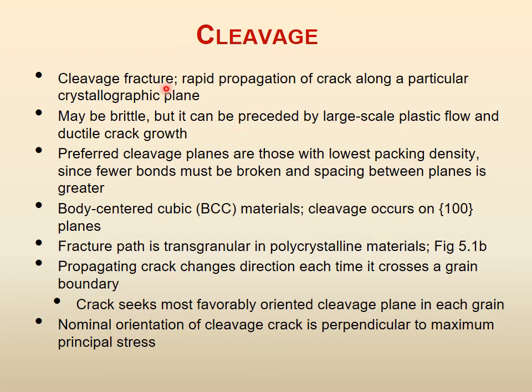One thing is that cleavage can be totally brittle. There is a big fracture all through and there is a cleavage surface. But on the other hand, there may be large scale plastic flow and ductile crack growth, and because of some sudden change in mechanism, now all this has changed to cleavage. So originally there is large scale plastic flow, which means ductile crack, and suddenly it changes into cleavage. So it could be totally brittle, or it could be preceded by this and then change into cleavage.